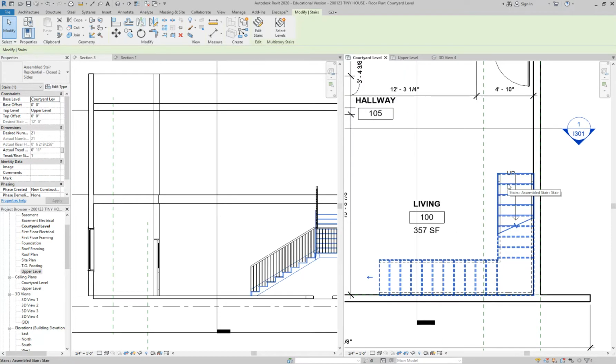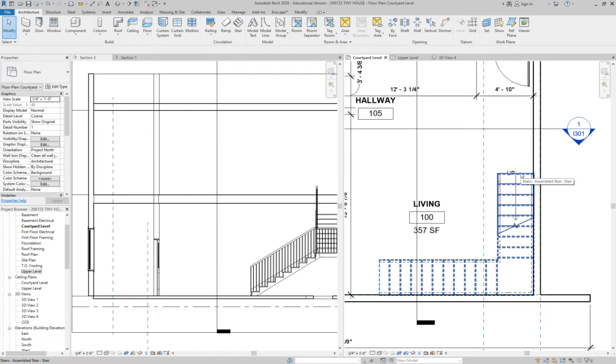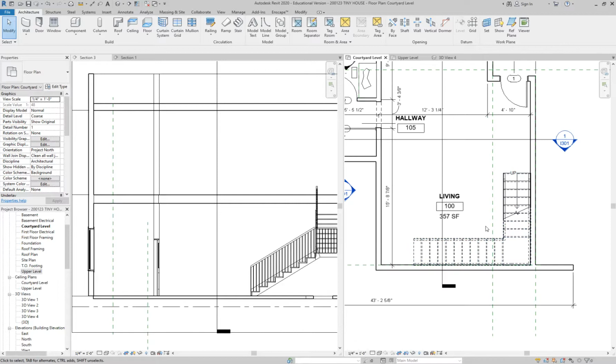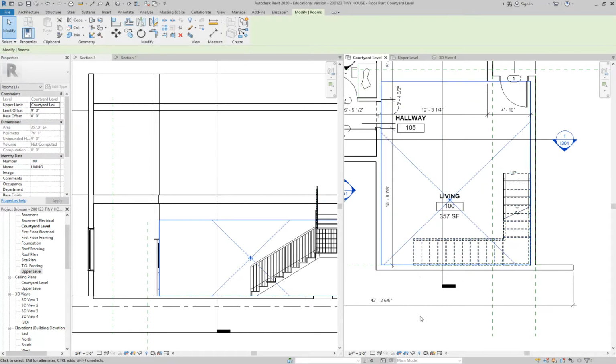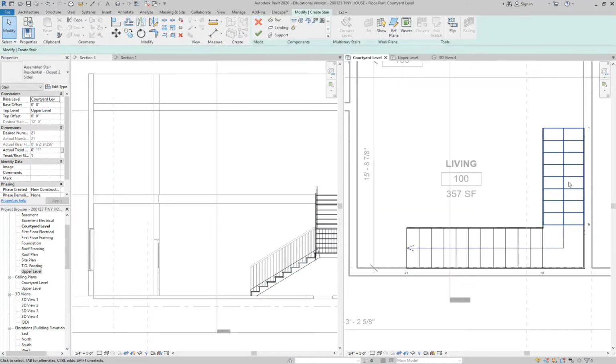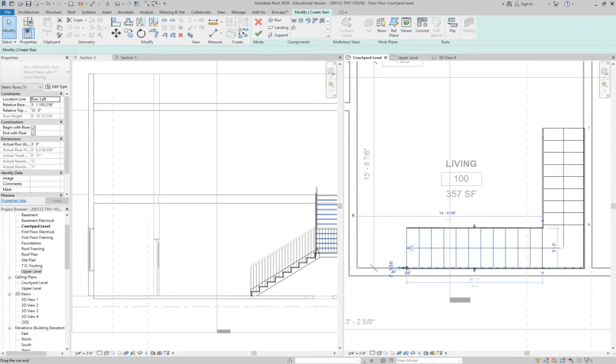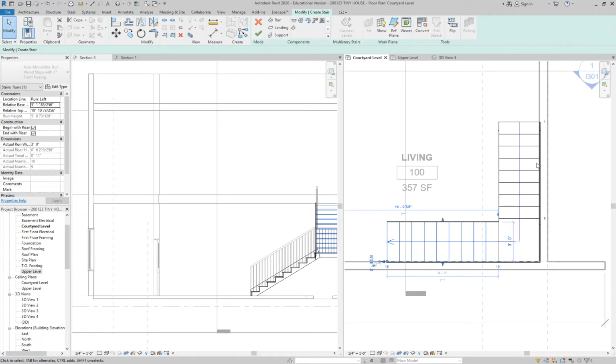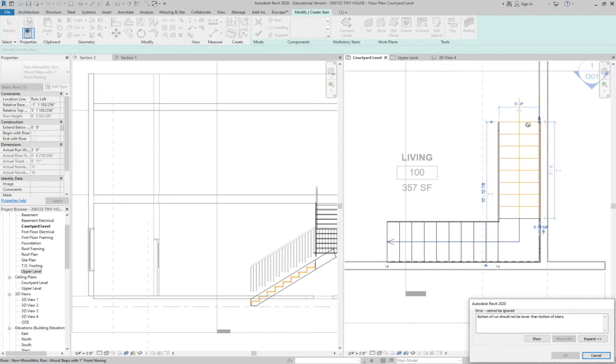And the reason why, whenever I go to edit the stairs, let me show you what happens. Let's say that on the upper level I want to have more stairs down here. When I click on edit stairs, you will notice that it's numbering it. Here's the first stair, 9th, 10th, whatever. I can take stairs away, and it's like, okay, you just need to add more stairs somewhere. But if I come here, it doesn't let me add stairs that way.